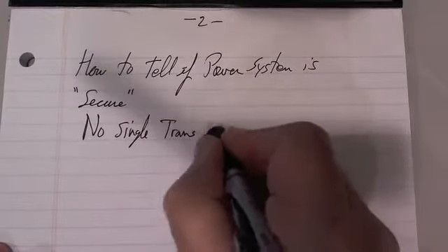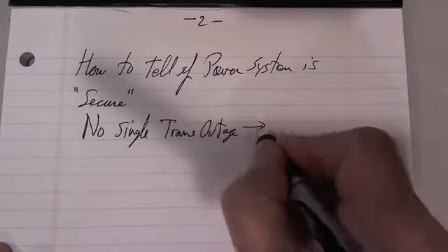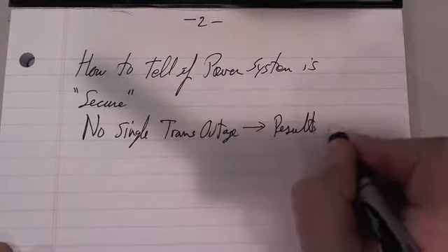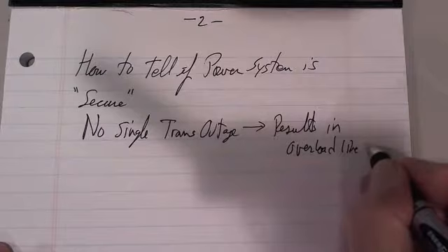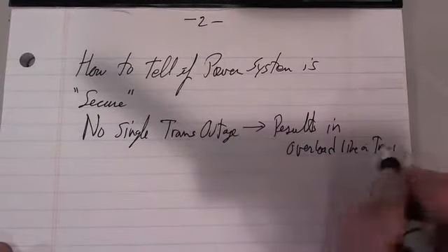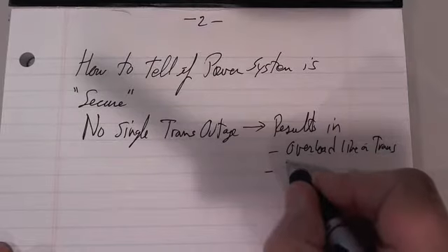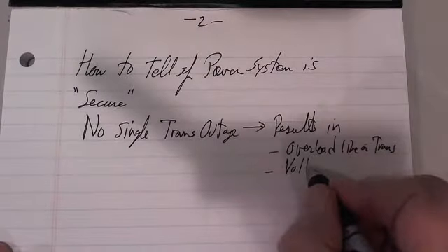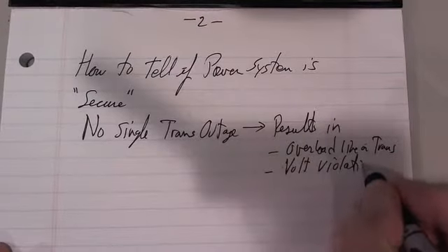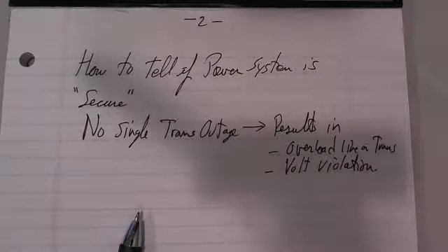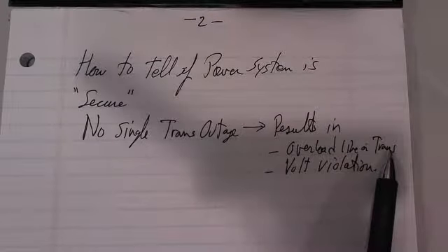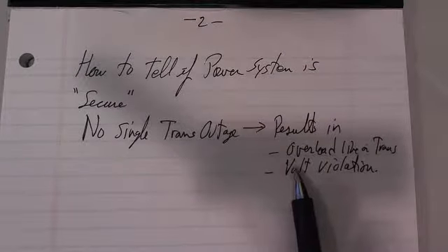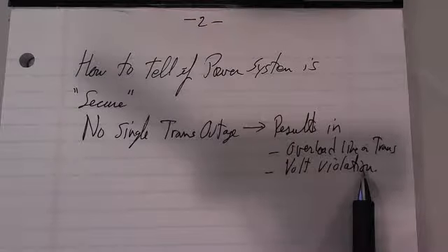transmission outage results in an overload on a line or transformer, or, particularly what we're worried about, a voltage violation, typically low voltage. So if a transmission line goes out, none of the flows on the system become too large, and none of the voltages drop too low.